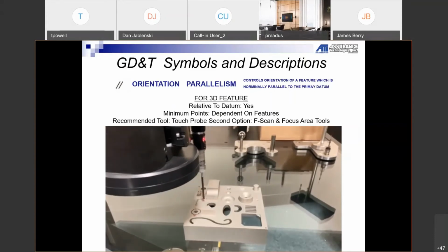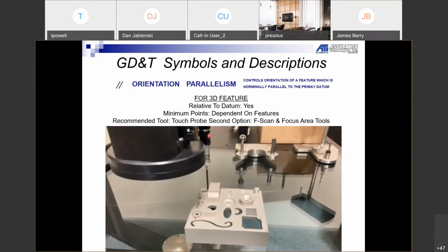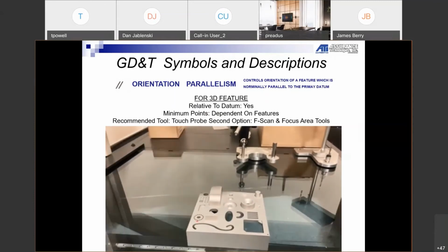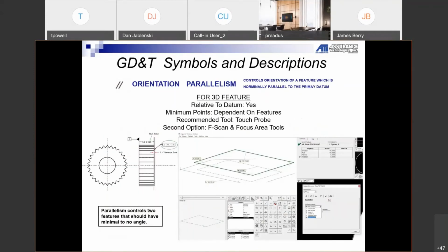If they're using vision, you can use vision, just so your numbers correlate on there. We have one customer whose supplier only has a CMM, no vision, it's only touch probe. So they are building their styli and touch probe library to be able to compare apples to apples with their reporting on there.